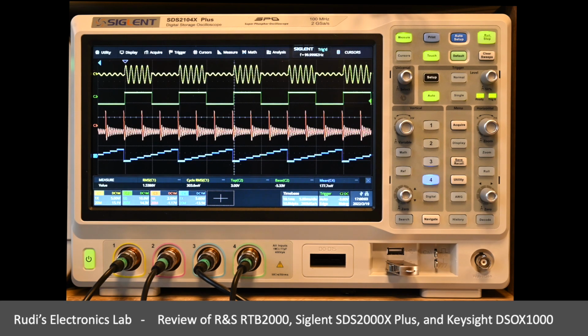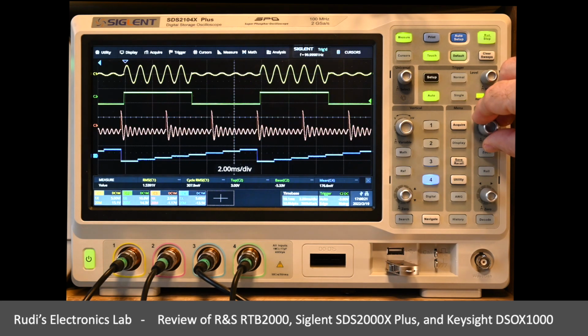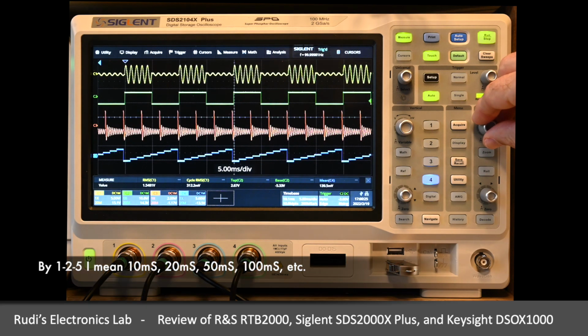There are further ways to work on exactly which part of the waveform we're looking at. Maybe I should mention that the time base is not a super good idea for this, because Siglent, and I find that a little bit weird, does not have a fine position for the time base. So I can change the time base in big steps, 1 to 5 steps, but I cannot click it and then do small steps like almost any other device that I've ever worked with.